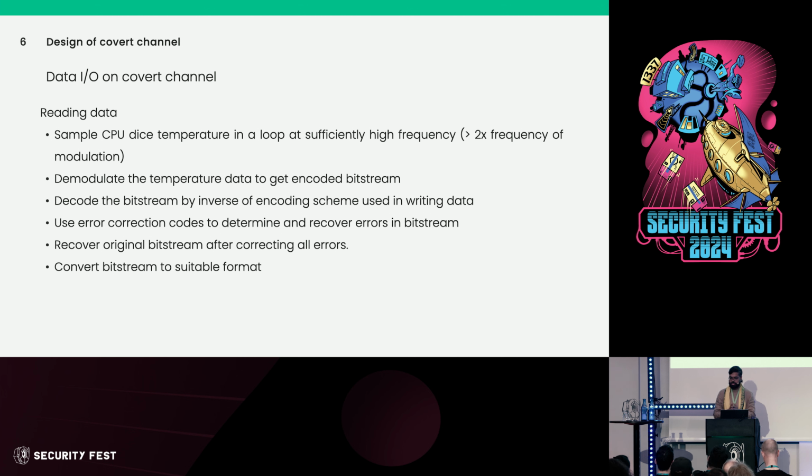It basically says that you need to sample at more than 2 times the frequency of modulation if you want to recreate that signal reliably. And that is why when your headphone is producing audio output of roughly 20 kilohertz, your recording equipment is sampling the audio data at 44.1 kilohertz. It is following that Nyquist theorem.